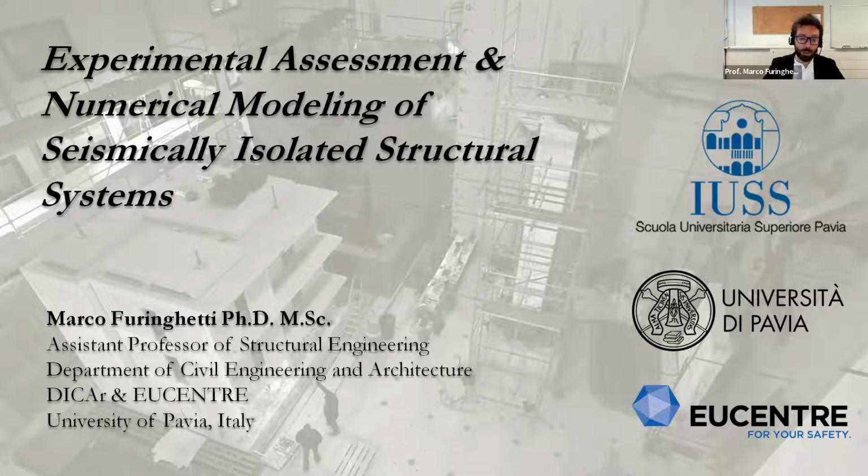And we always have to check also the main cause of the flexibility of the structural system. Because maybe if it is a high-rise building, what I mentioned, the uplift rather than the tensile forces in the bearings, rather than soil structure interaction, maybe we can also provide some base isolation. So any other questions?